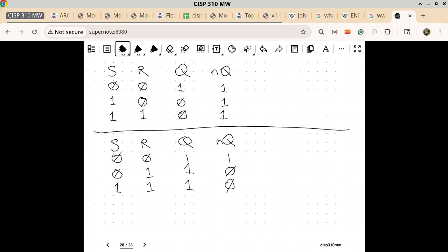It's latching. Exactly. This is why it's called the SR latch, because it's latching the previous state. When it's a zero, you're changing the state, but when both inputs are ones, all you're saying is, I'm not changing anything, just keep the current state. Whatever there was, keep it. Is that okay? All right.